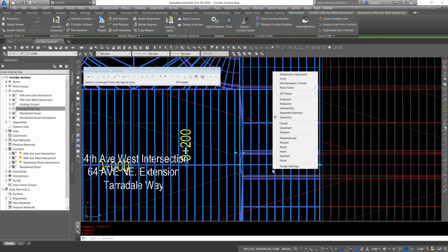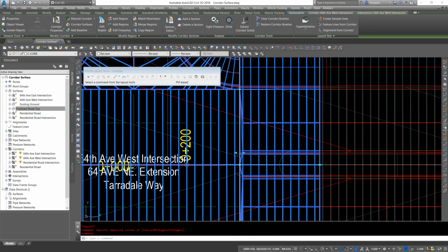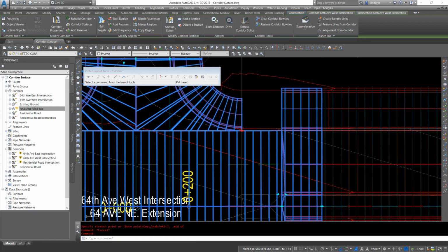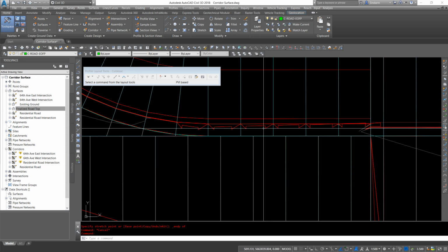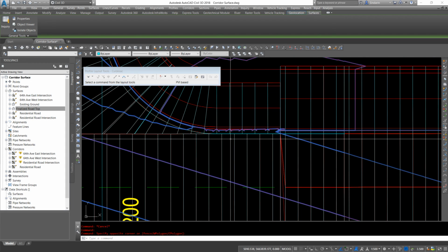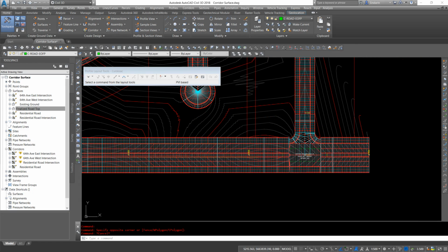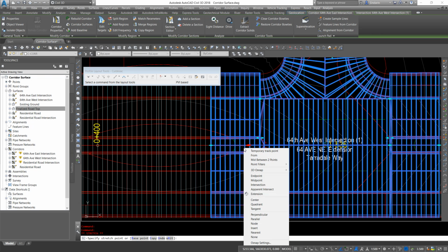This side we're going to do the same. I'm going to make sure you click on the grip. Midpoint of the circle. Take this, go to the end point. A quick rebuild. Again, some minor triangle issues. And we'll do the same with this one.